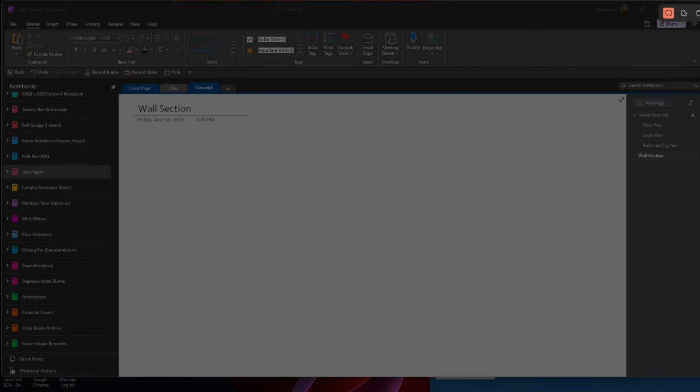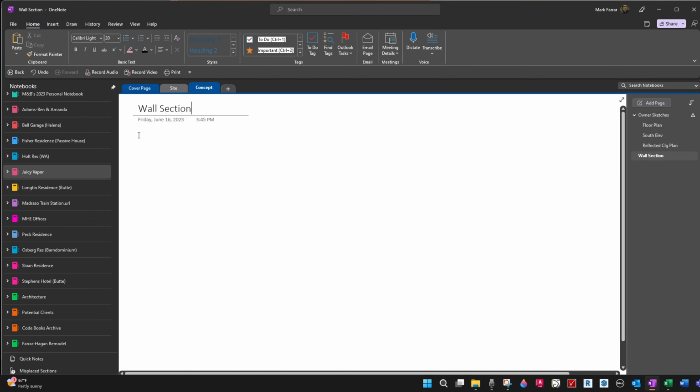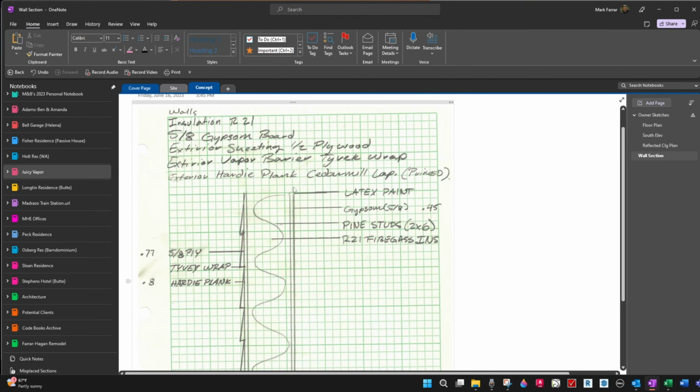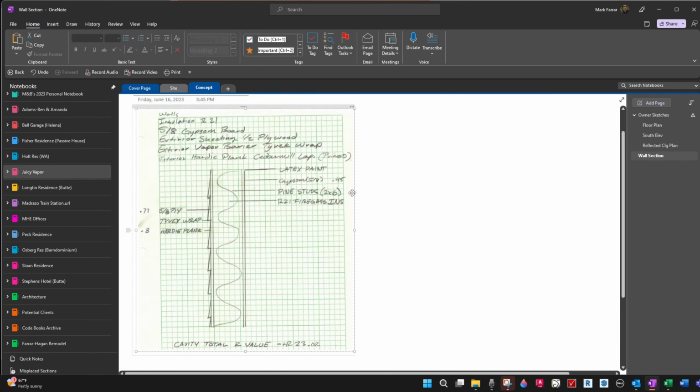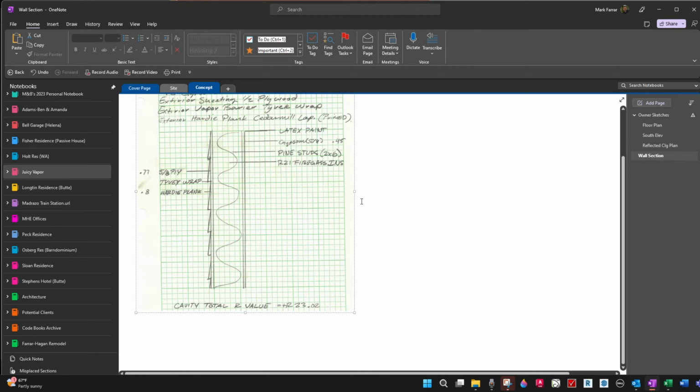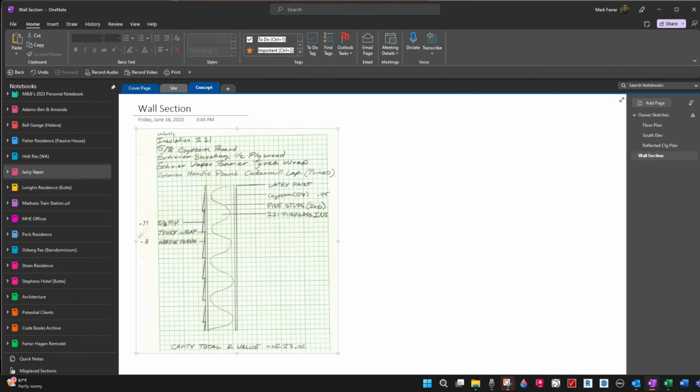But I'm going to go out there tomorrow and photograph this place, take off some of the skirting, and take a look and see what we've got underneath. So my understanding is that this thing may be on concrete piers, which means I may have to design it so that the new structure is independent of the existing building.